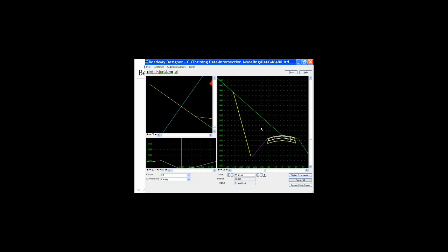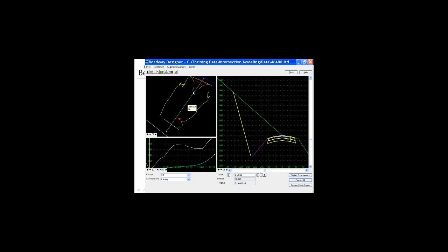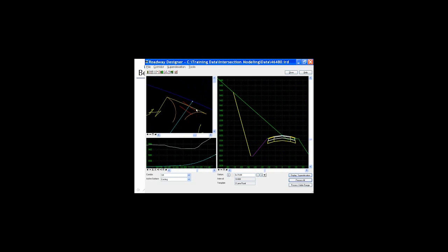So now if I do a process all, notice how the corridor is clipped along the edge of pavement. But I'm just shy of the edge of pavement. That's because I'm attempting to maintain the integrity of the features that control the components for the mainline paving. So let me finish this up by going in and making sure that I have my target aliasing taken care of.